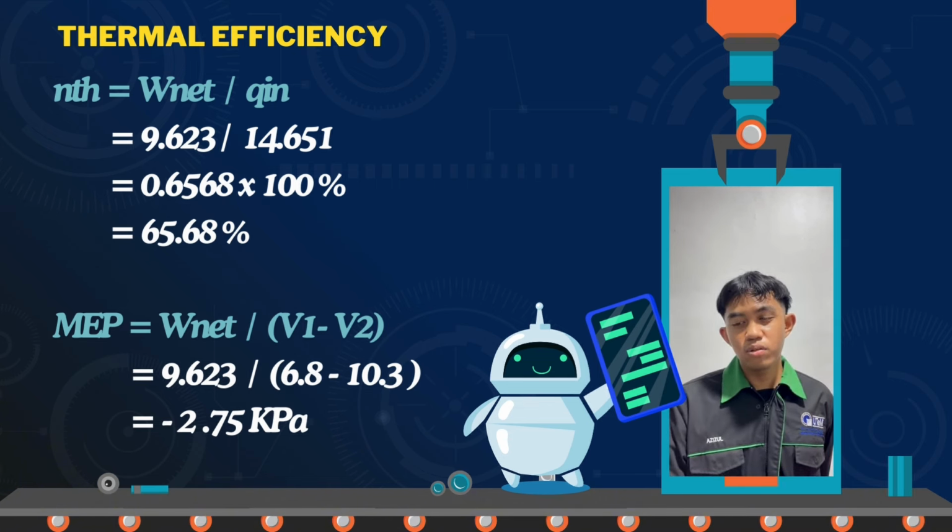From the journal of advanced internal combustion, there are some suggestions to improve the system. First of all, ultra high pressure injection. High pressure injection can improve engine performance and reduce emissions by increasing injection pressure from 100 megapascal until 160 to 180 megapascal, and even over until 200 megapascal. This decreases fuel consumption and increases engine efficiency, improving the brake thermal efficiency and fuel consumption. It also facilitates quicker heat release, shorter combustion phase, and faster fuel atomization.